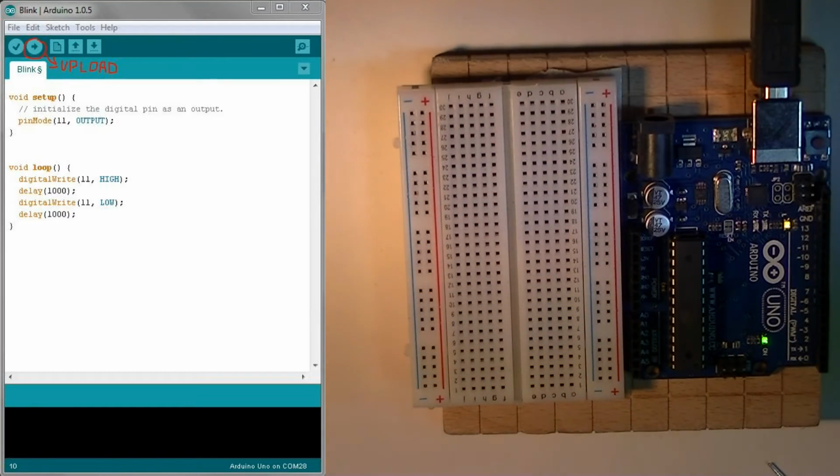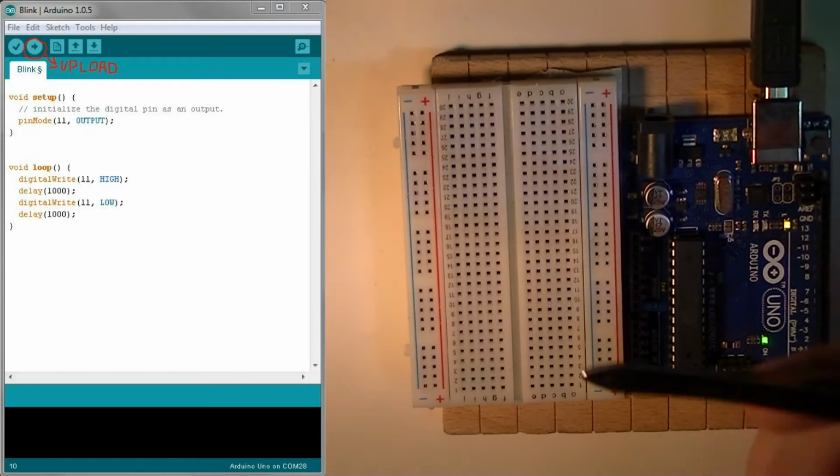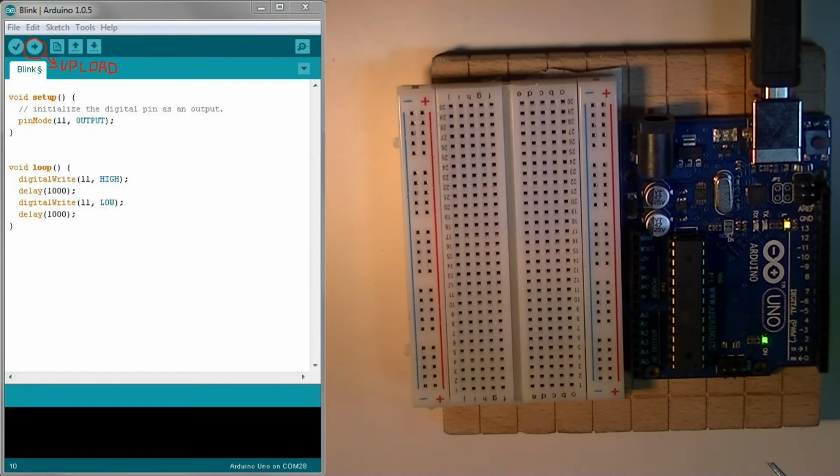Okay, so let's get started. This is the simplest ever Arduino circuit, simplest ever programmed circuit, should I say. On that side of your screen is the program. As you can see, it simply is going to turn pin 11 high, wait for a second, 1,000 milliseconds, 1 second, and then turn it low. Effectively, that is going to make pin 11 go on and off.